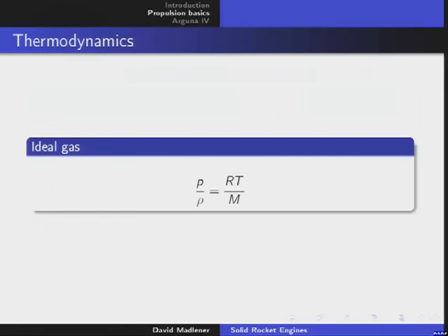No? So all of these equations always describe the ideal gas, the pressure of the ideal gas. Yeah, and you have only to keep one thing in mind. The pressure is proportional to temperature. The higher the temperature in the rocket chamber is, the higher the pressure, the higher the thrust, and the lower the molar mass. That is, the smaller the things that come out of the chamber, the better, yeah, the higher the pressure.